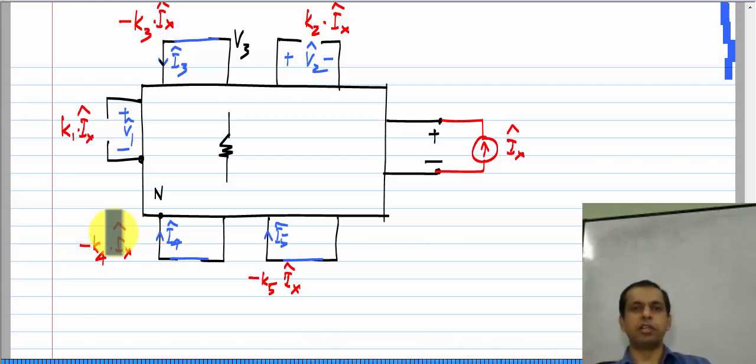Now, it turns out that in circuit analysis in particular, you have something known as noise analysis. Every resistor in the circuit, in general any component in the circuit creates noise and you need to calculate the transfer functions from every noise source to the output and multiply that by the actual noise being created to find the output noise.